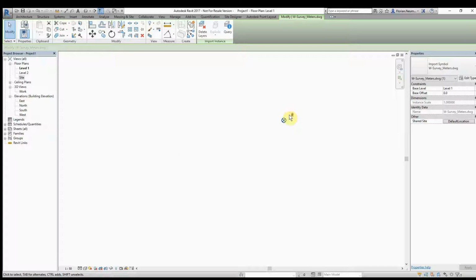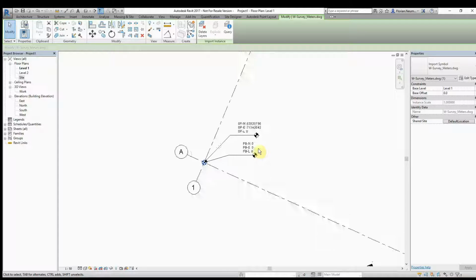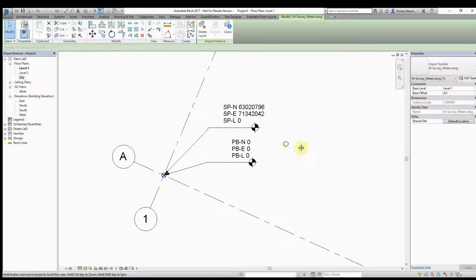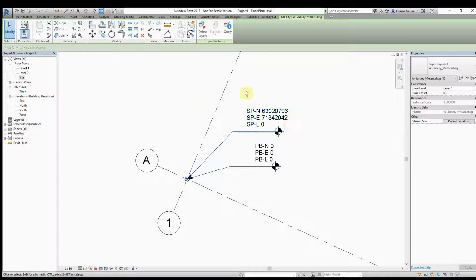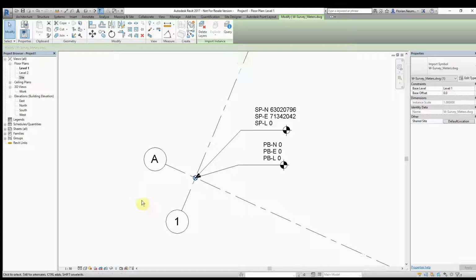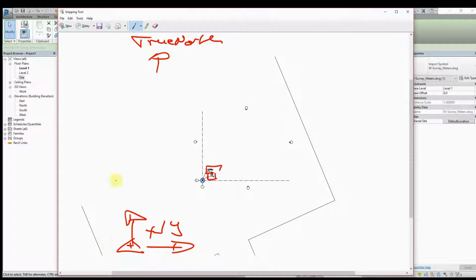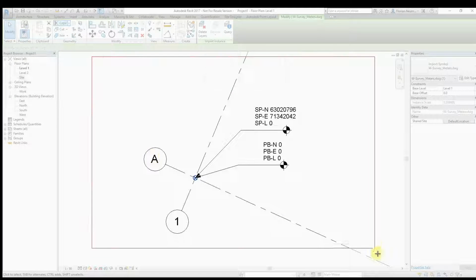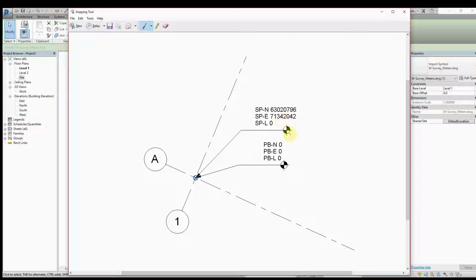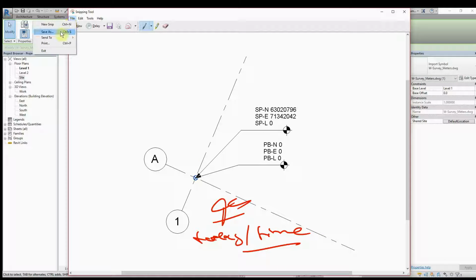Good. So whenever we have something in place, the best and the easiest way, and you have your origin here, is to coordinate your model just with some raster graphics within the project. And this means, for instance, that we just take a tiny snapshot. With this tiny snapshot, we can also sign it off, mention here something when this was, for instance, done today with a certain time. And then we just save this file here.